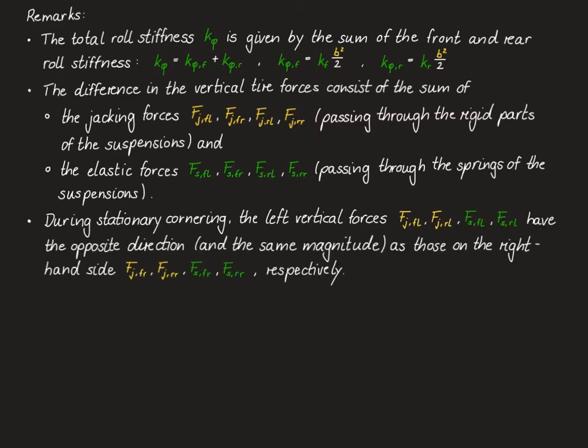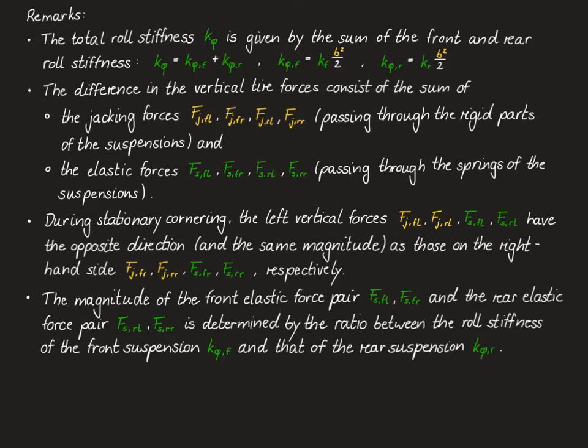Third, during a stationary cornering maneuver, all of the vertical tire forces on the left-hand side have the opposite direction and the same magnitude as the corresponding one on the right-hand side. And finally, the magnitude of the front elastic force pair and the rear elastic force pair is determined by the ratio between the roll stiffnesses of the front suspension and that of the rear suspension,